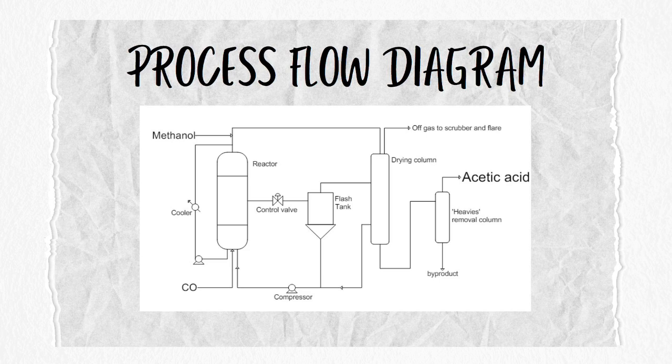Other than that, there is a cooler. The reaction mixture exiting the reactor is usually hot, maybe due to the exothermic nature of the reaction. So the cooler functions to reduce the temperature of this mixture to make it suitable for further processing.